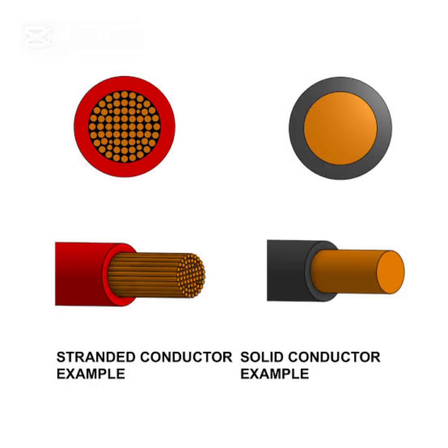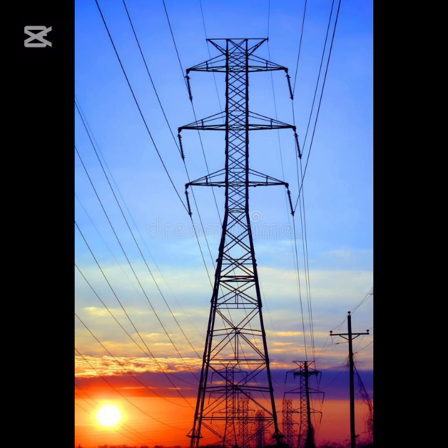4. Conductor shape. Different shapes affect magnetic field distribution and eddy current behavior, resulting in variations in skin depth across different conductor geometries. But friends, why should we be concerned about the skin effect, and how can we mitigate it in transmission lines? The skin effect presents several challenges, including: first, increased power losses and conductor heating, which decrease system efficiency and reliability. Lastly, higher impedance and voltage drops in transmission lines, affecting signal quality and power delivery.